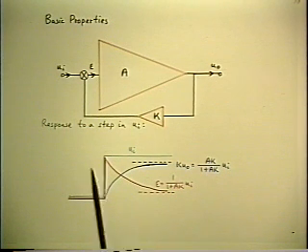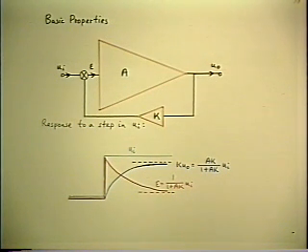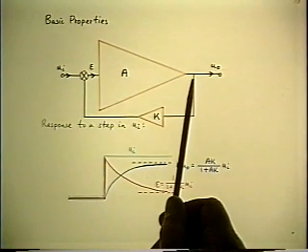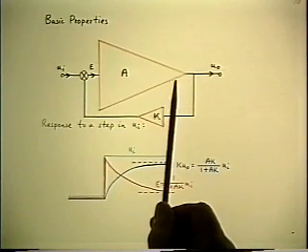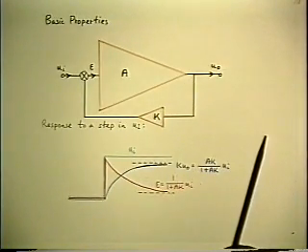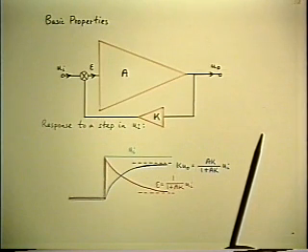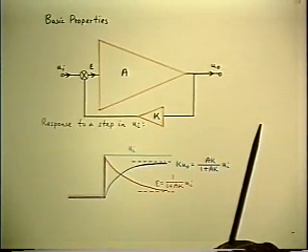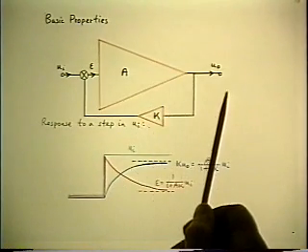Now, it's a little more useful to have this physical interpretation when you think of some typical numbers that may be involved in this. Suppose the forward amplifier is an IC chip. It's got loads of gain: 90 dB, 100 dB, 110 dB. Lots and lots of gain. The maximum dynamic range of the output is limited by the power supply, plus or minus 15 volts maybe, or in your case, plus or minus 1.5 volts perhaps. Whatever it is, it's limited.